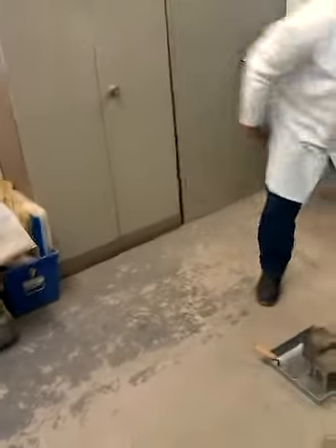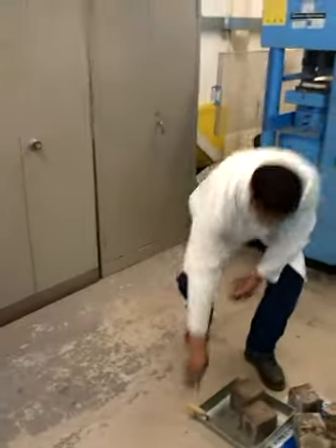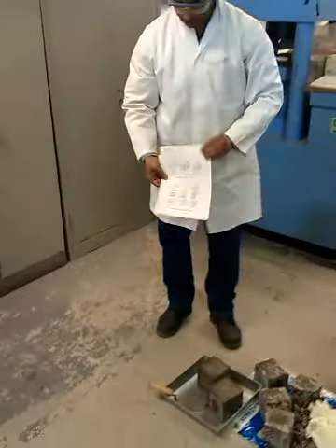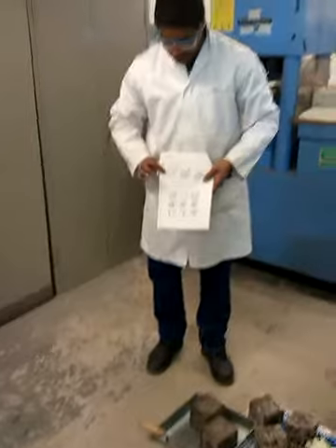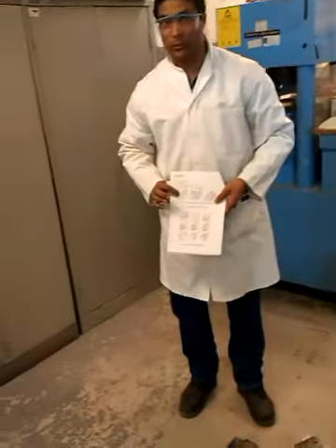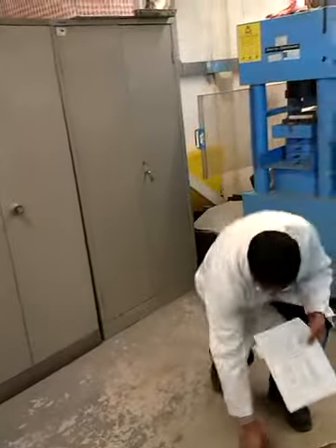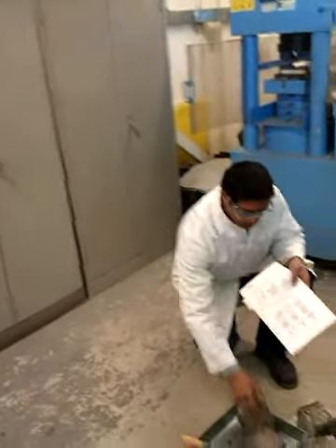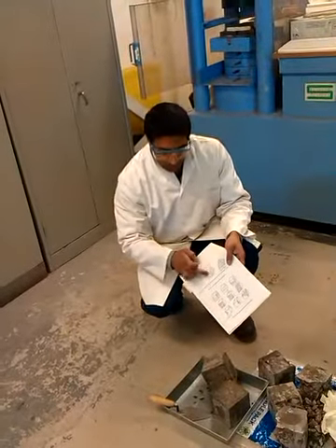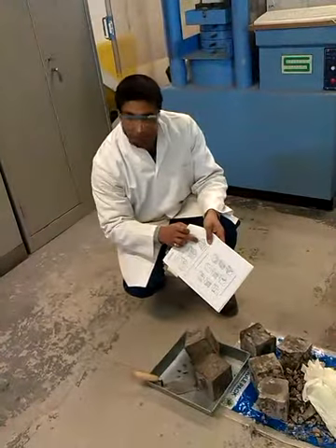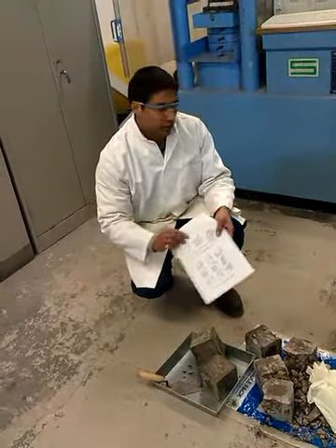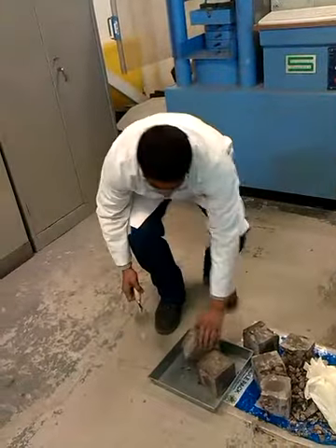Okay? Right. So now, for analysis of the concrete cubes, how it has been broken, the code will say the satisfactory and unsatisfactory test of the compressive strength of the concrete cubes. After testing, if the concrete cube looks like this one, the zigzag way over here, that's fine. And if you peel that off, you will get the conical shape like this one. And again, if you take part of that one, you will get the pyramid shape. If that is the condition, then that is the satisfactory testing of the concrete cubes.